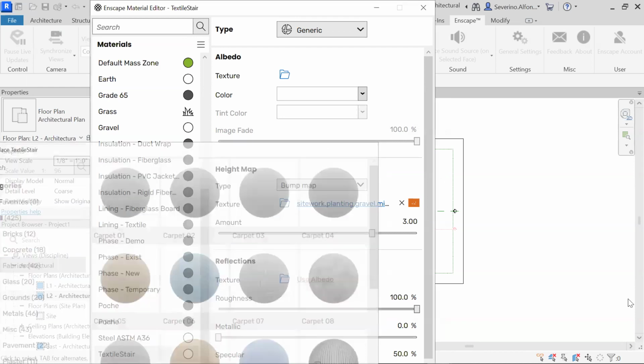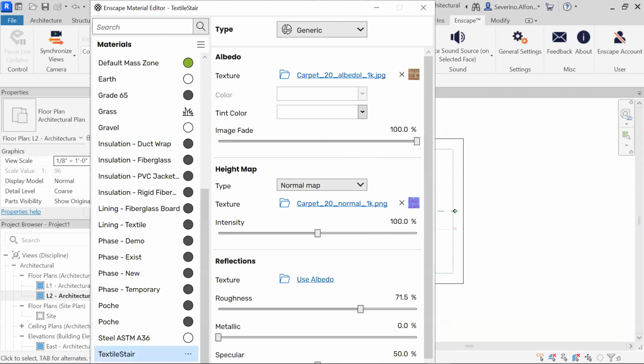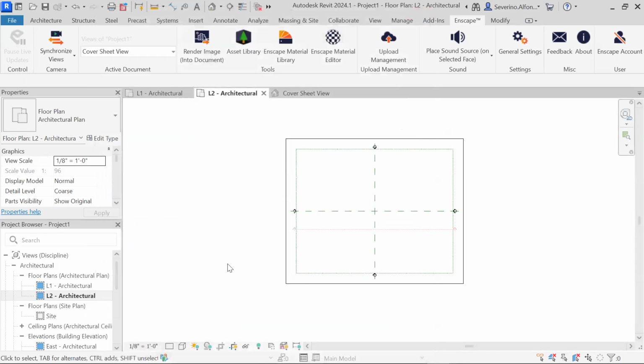When you replace, the text out there keeps the name, but the information behind it is the other material. So again, that's an option you have to replace the Revit material with the Enscape material. Okay, so once you have that, whatever object has that material assigned will take the material information from Enscape if you're rendering with Enscape.